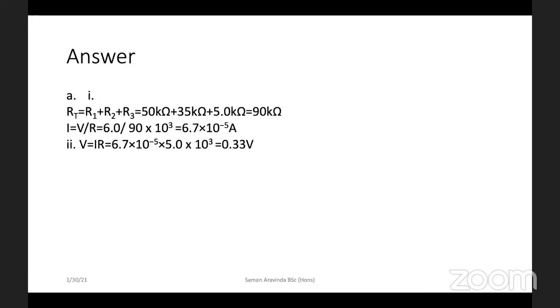So the voltmeter is not connected across the LDR. It is connected across the fixed resistor. So light intensity increases means the resistance of the LDR reduces, so that reduces the potential difference. However, all these potential differences add up to 6 volts. That means across the other two, it should increase to compensate for the reduction.